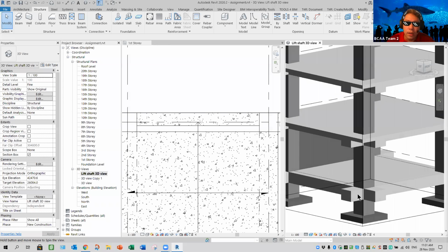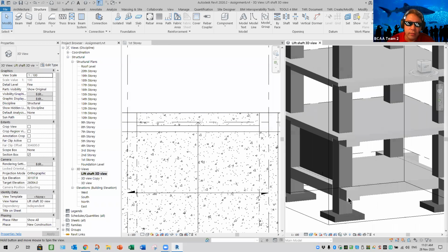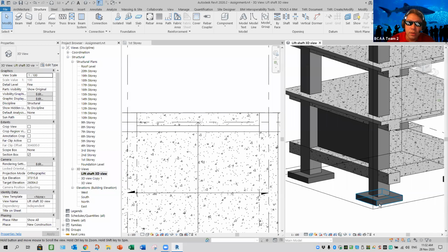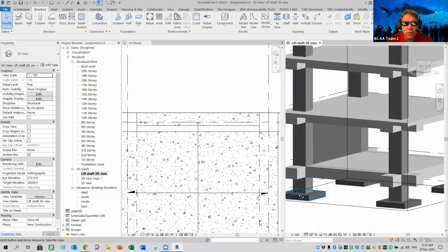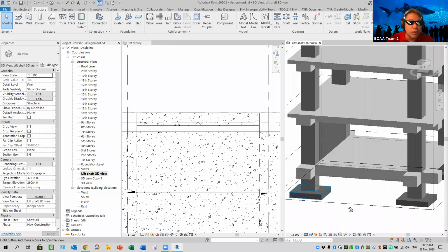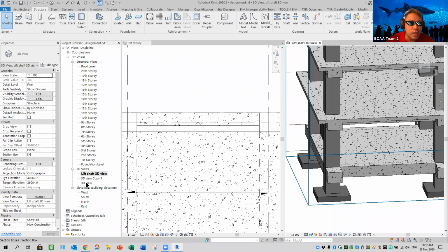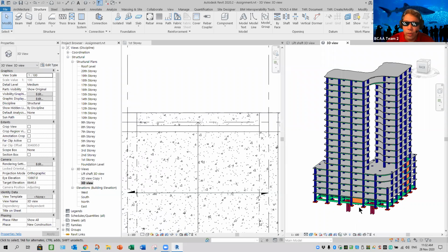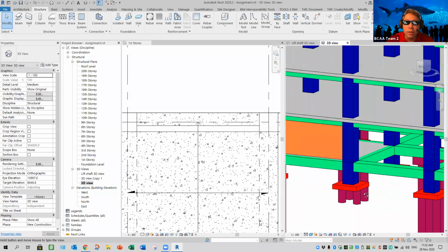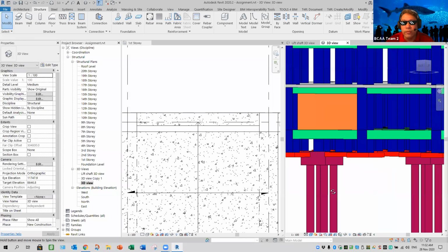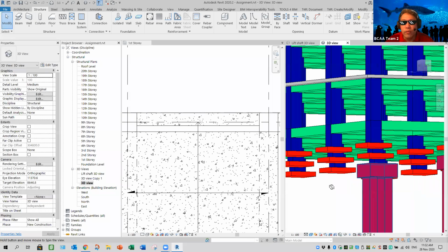Because in this view, we didn't apply the view filter, so it sticks to that specific view. The important thing is that our main 3D has it. That's more important. See that? When you create, it's already there. So no need to keep attaching all this color filter for every view.